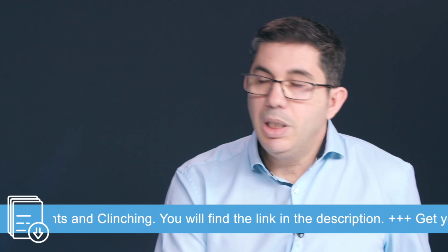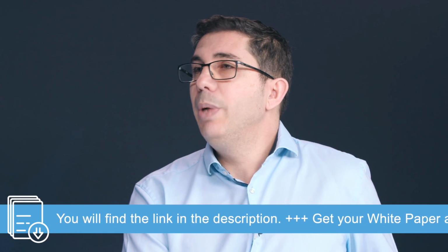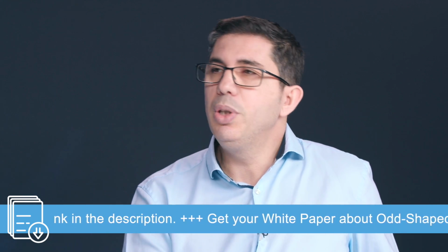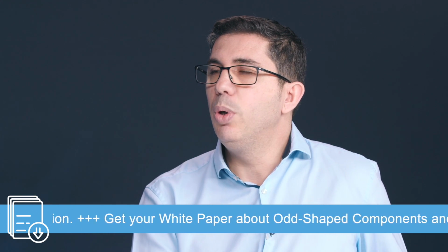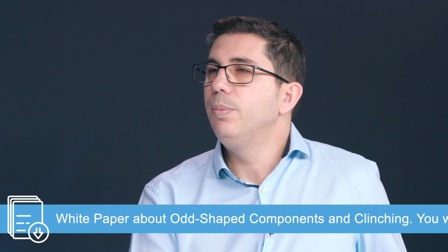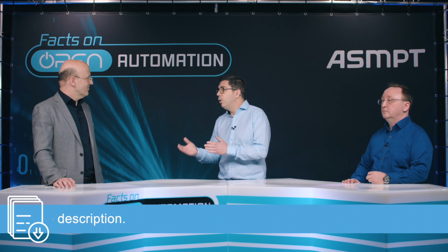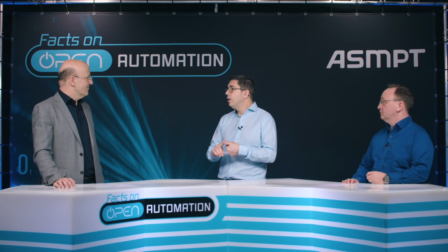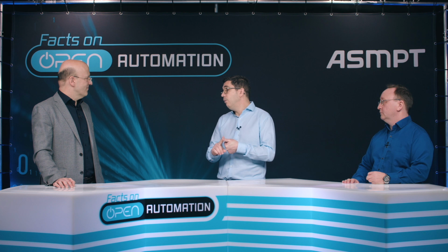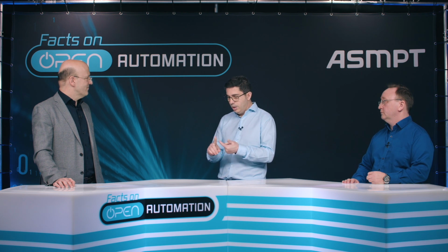Yeah. In a nutshell, the trend is automation. So previously, manually placed components shall be placed now on a standard SMT machine. The reasons why these components have been placed manually are the following: size, they were out of the machine specification.